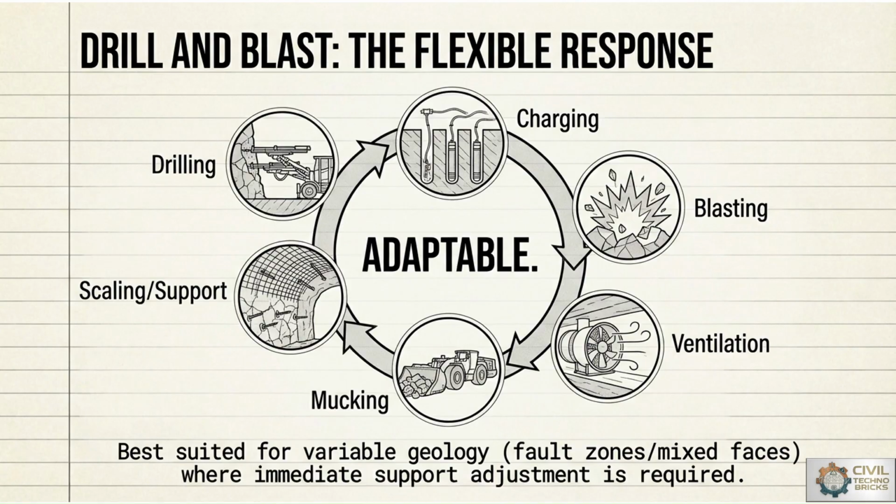So we have to provide ventilation for the persons who are working in that premises or in that tunnel. At the same time, ventilation also provides safety to the workers. We have to use some advanced machines or tools or loaders or muck removers for the mucking procedure, and we have to provide scaling and support by using the grouting method or bolting method at the end.